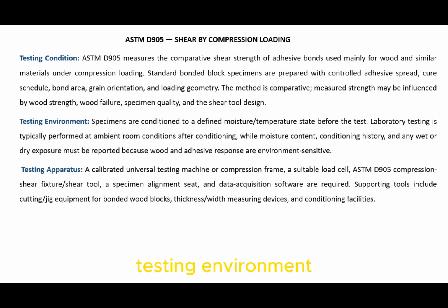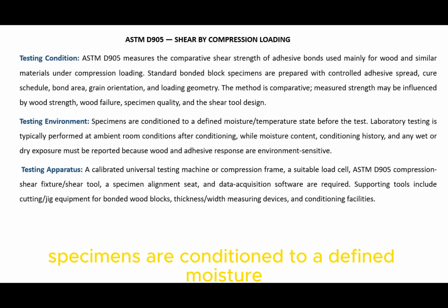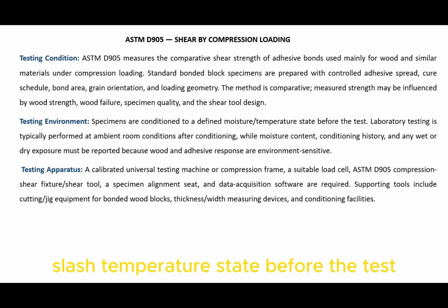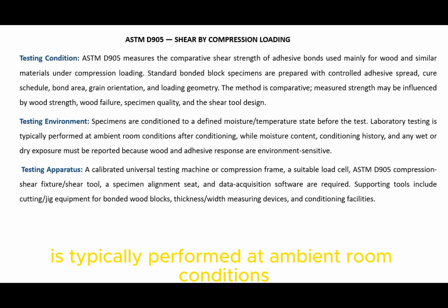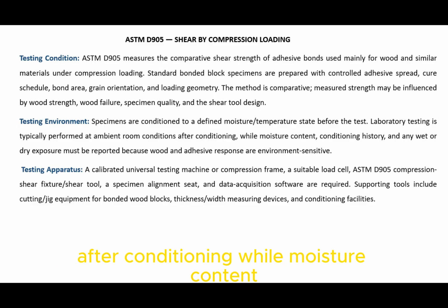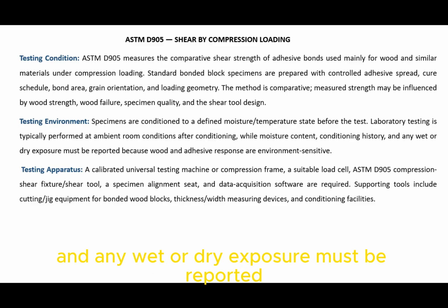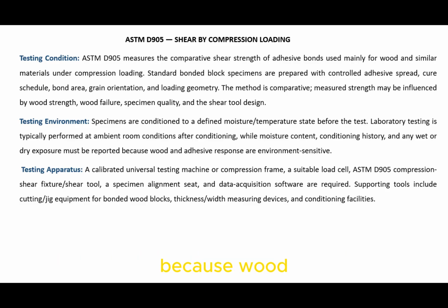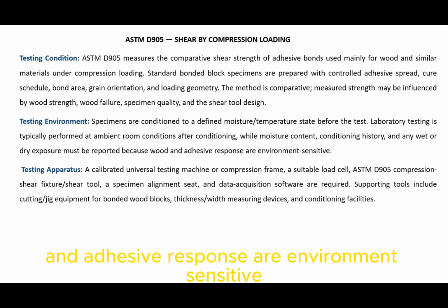Testing environment. Specimens are conditioned to a defined moisture/temperature state before the test. Laboratory testing is typically performed at ambient room conditions after conditioning, while moisture content, conditioning history, and any wet or dry exposure must be reported because wood and adhesive response are environment sensitive.